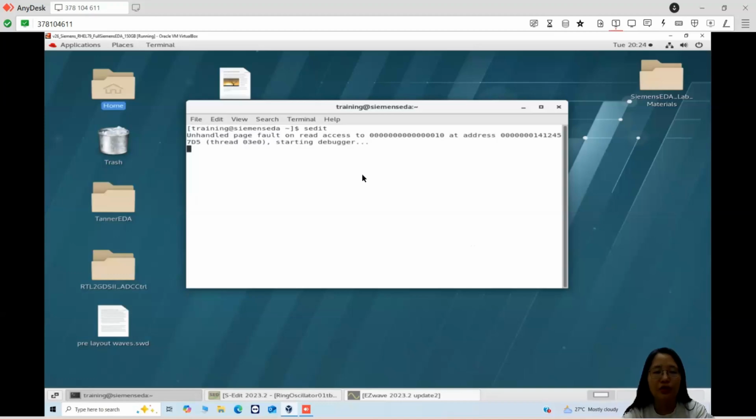I'll do the demonstration for project 3. Project 3 requires me to design an n-stage ring oscillator using the NAND gate as the single buffer to activate the oscillation system. First, I will show you my inverter design in terms of schematic and layout.